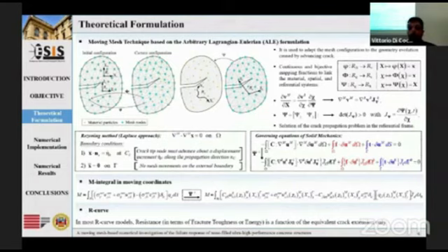The M-integral expression, starting from the J-integral, is applied to a superimposed state formed by two admissible fields, the actual one, for which the stress intensity factor would be evaluated, and the auxiliary one whose solution is known. Finally, in the R-curve model, the fracture resistance, expressed in terms of fracture toughness or energy, is a function of the equivalent crack extension only.